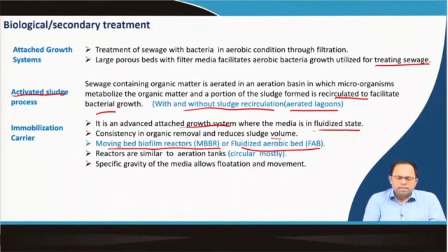So, these reactors or chambers where this reaction takes place are similar to aeration tanks, and the movement is mostly circular, and air actually helps in their movement. The specific gravity of the media allows flotation and movement, because in most cases we would be using HDPE or plastic media. So, they usually float in the wastewater, and that is why they move around in it.